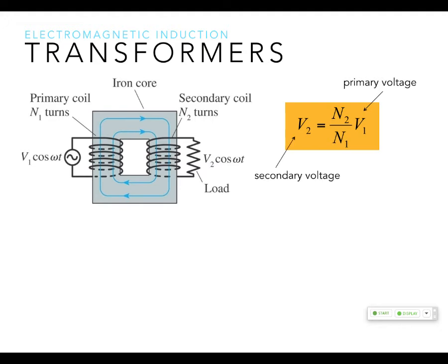When are transformers useful? Well, stepping up and stepping down power. Where do you want high voltage? Power plant. Not actually so much power plants. High voltage is really useful for transferring power because you have a lot less loss if you have a high voltage power line, right?